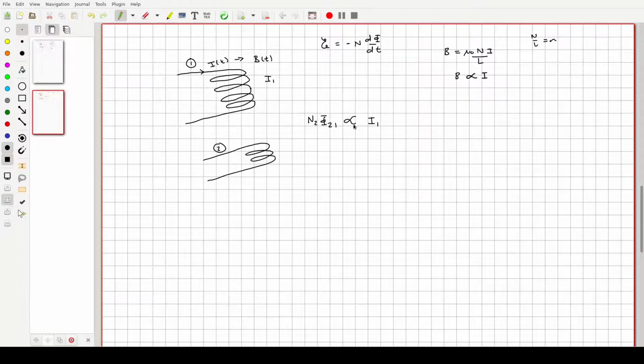proportionally, the amount of magnetic field. So this right here really is the relationship between the current in number 1 and the induced effects in number 2. And so what we do is we put an equal sign here. We put a constant proportionality, which we call M, which is the mutual inductance. So N2 phi 21 would equal M21, that's our constant, times I1.